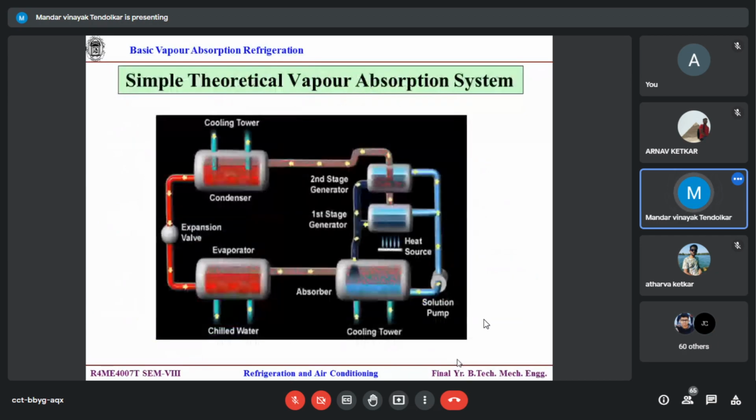So this is the animation for the actual vapor absorption system. Can the online people see? Because here I can see it clearly. Yes. So now you can see over there, the condenser, the throttle and the evaporator remain the same. What we have exchanged is the compressor. Now there is a heat source, that is our generator. Look at the bottom side, it is an absorber. So the refrigerant, red color, is getting absorbed, and the absorbent, blue color.